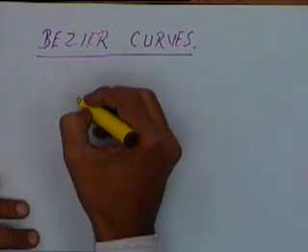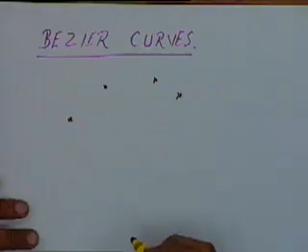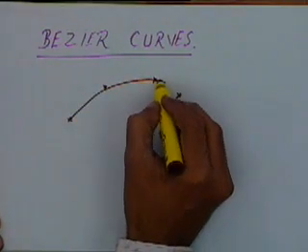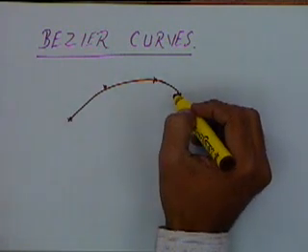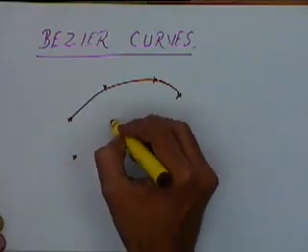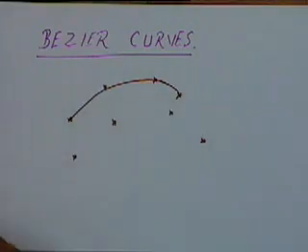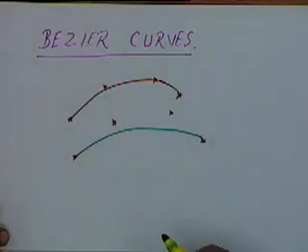See, so far when we talked of a 4-point form of a curve, our cubic curve was passing through these points like this, as we are doing an interpolation between these points. Now we will define a curve which does not pass through these points, but is only an approximation amongst these points. So we say that it is an approximating curve and not an interpolating curve. The curve will look like this.